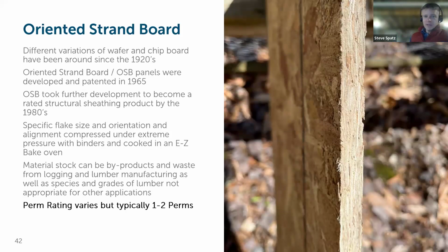Alternatively, OSB is that concept I brought up earlier. You're taking trees, turning them into bulk bark mulch, and then compressing them into a usable form. There's a lot of glues, binders, and other components that create the material in the form that we use it. As a consequence, there's a very limited capacity for the wood component of this to transport moisture vapor, so it's a low perm material. So there's a consideration in choosing CDX plywood versus OSB in a wall assembly, depending on the other materials you're going to put in and around it and behind it.